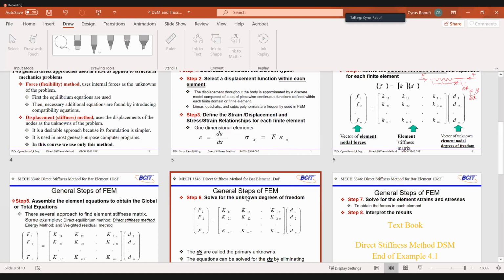Design verification, or rather, I think it is better to use FEA verification and FEA validation. What was the difference? The difference was in validation, you need to have a physical test in order to validate your FEA model. That was the meaning of physical validation. You need to have a physical test.